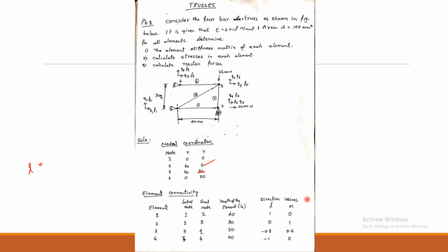In the same way, the next part is the Young's modulus. As I said, Young's modulus as well as cross sectional area are the same for element 2 also. And let us look into the global connectivity. So global connectivity for element 2 is, since it starts from node 2 to node 3, Q3, Q4, Q5, Q6.